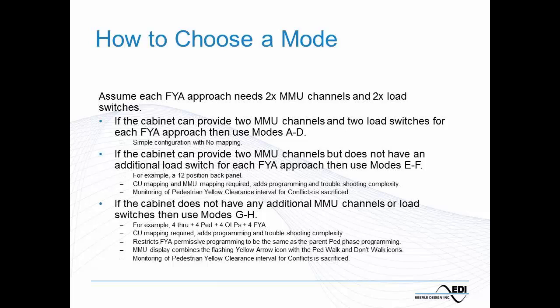There's another restriction here: the permissive programming for the flashing yellow arrow channel has to be the same as the parent PED phase programming. Ordinarily, this is the case, but depending on the geometry of the intersection, we may find it's not the case. In that scenario, modes G or H will not work.